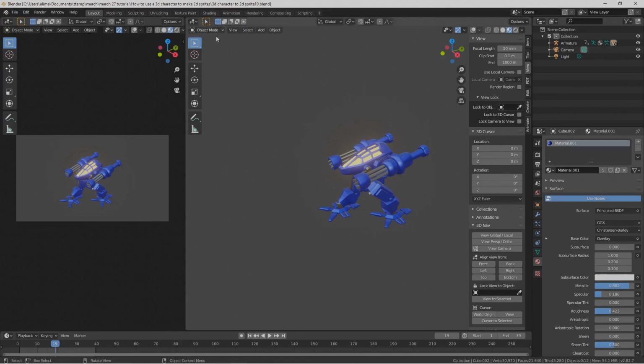Okay, what we're going to do now is select the edge of this rectangle, which represents our camera. If you select and don't see anything, see these two circles here? You're going to left click there, and that turns on the things that normally don't render in Blender. That's on by default.